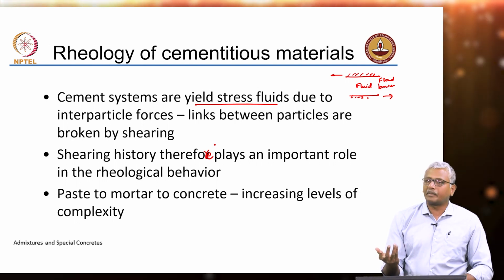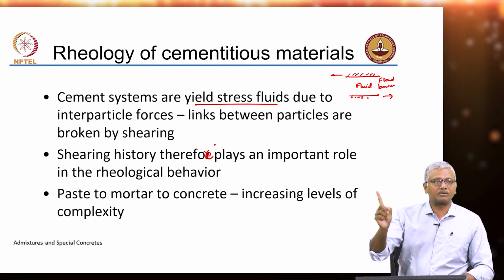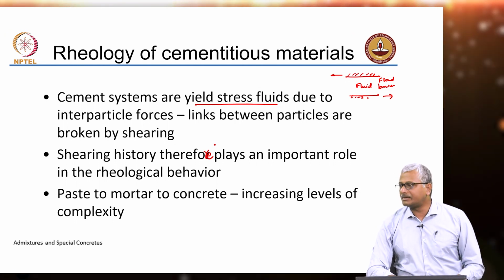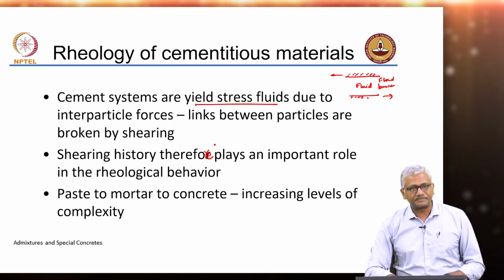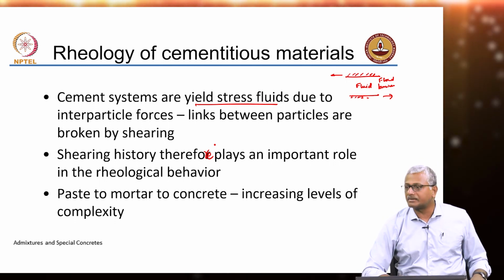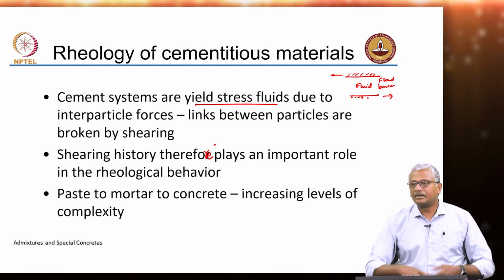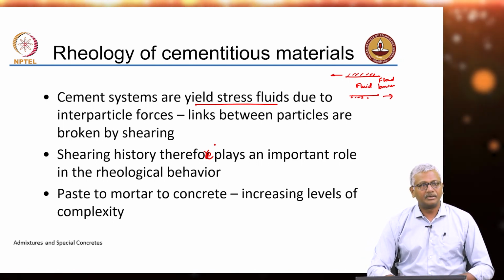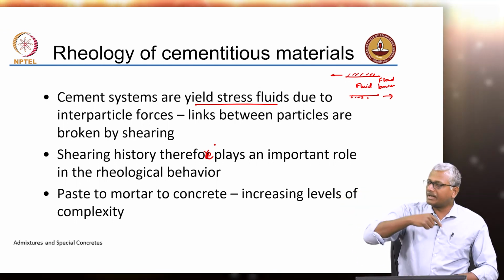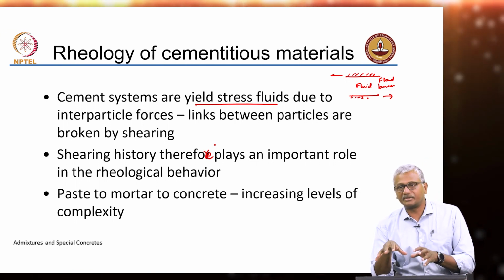So, in concrete, what happens? The concrete in the ready mix plant gets mixed in the concrete mixer there, then it gets transported in the truck. Now, in the truck, if the concrete remains stable and travels about one or 2 hours to the job site, after that you need to again break that stability by agitating it, right? So, depending on how well it was mixed in the beginning, your level of agitation that is required to get it to a certain consistency will be different.